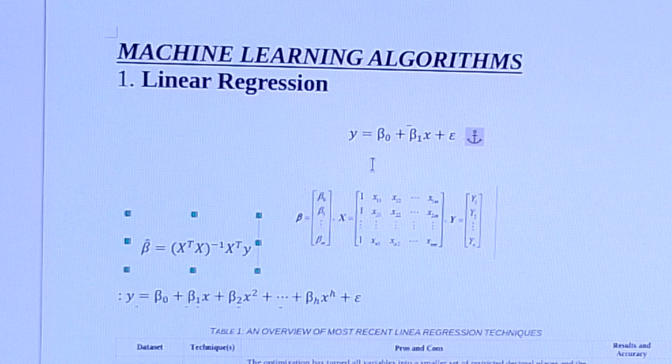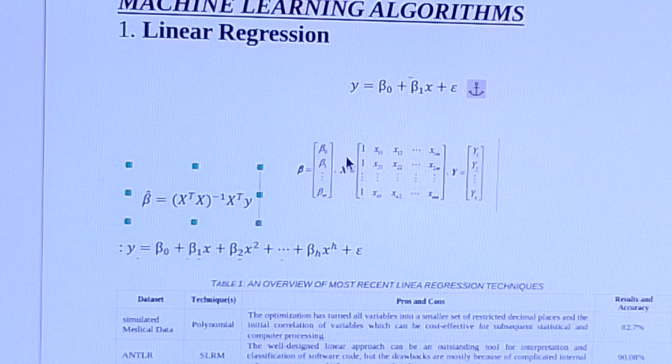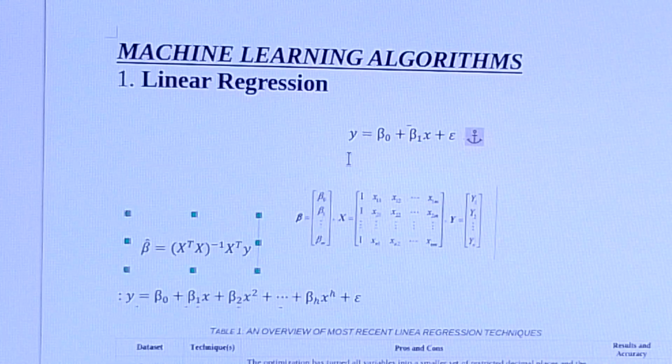Now, Zhu and Feng centered on the 110 kilovolt high voltage switchgear contact temperature results. Using the map-reduce model, the temperature regression model is developed by MLR, multivariate linear regression, to analyze and process the monitoring point data. The effects of the estimation are evaluated by the F regression criteria.